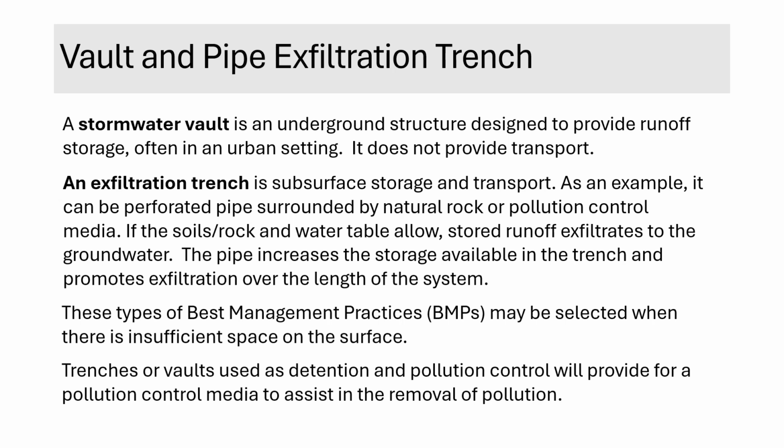When used for detention, they help manage peak discharge flow rates or attenuate the hydrograph, slowing down the release of water. As a retention system, they are designed to facilitate the exfiltration of stored water. For both detention and pollution control, these systems often incorporate specific pollution control media to assist in removing contaminants from the runoff. Ultimately, these types of best management practices are frequently chosen when there isn't sufficient space available on the surface for other stormwater management solutions.